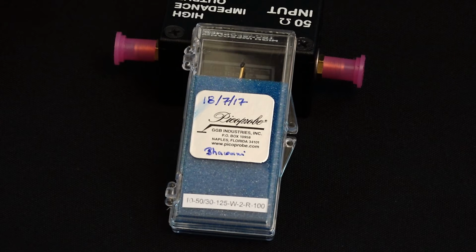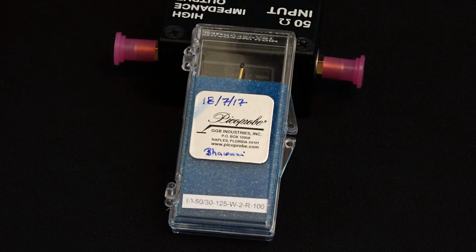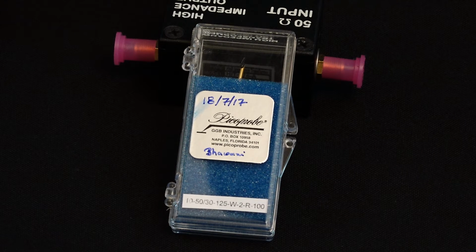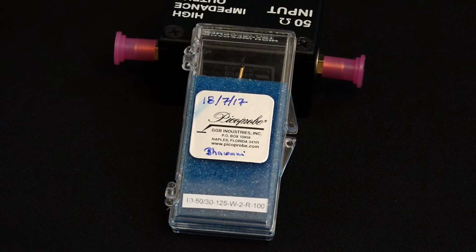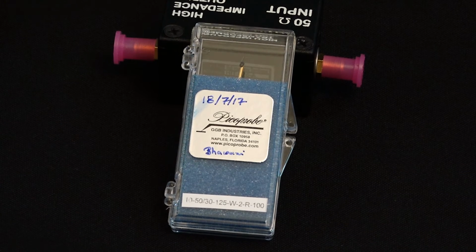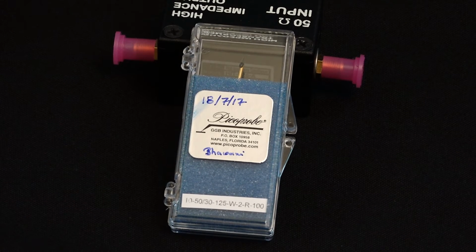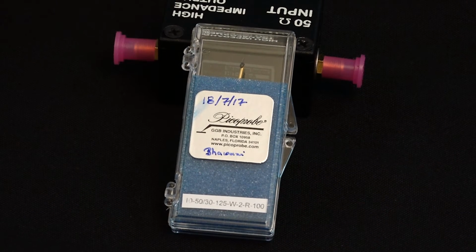Some important things you have to take care of while using these probe tips: one, as you can see, these probe wires are very thin. It's only 125 micron thick. So obviously you will have to be very careful when handling the probe wires. I cannot tell you how many probe tips we have damaged over the years just because of a bit of careless handling on the user part. So that's one thing, you have to be very careful.